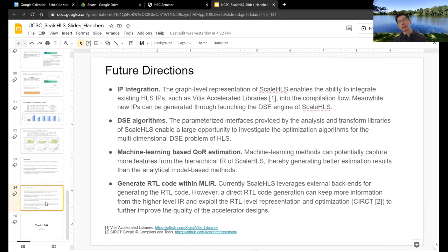So basically, from a high level, we are doing scheduling by analyzing the IR. You have an IR there, and you can analyze all the dependencies, including the SSA def-use chain and the memory dependencies. And on top of this analysis, you can do a scheduling. For now, we are doing ASAP/ALAP scheduling on top of the IR.